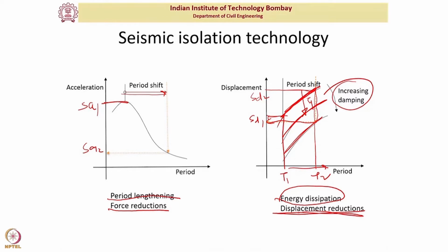Let us say you estimate some loads, and you estimate the live load, and you know that there is certain uncertainty associated with that. Those factors would still need to be there, because the uncertainty associated with the load is taken into consideration with the load factors, and the uncertainty associated with the strength of material is taken with the strength factors.